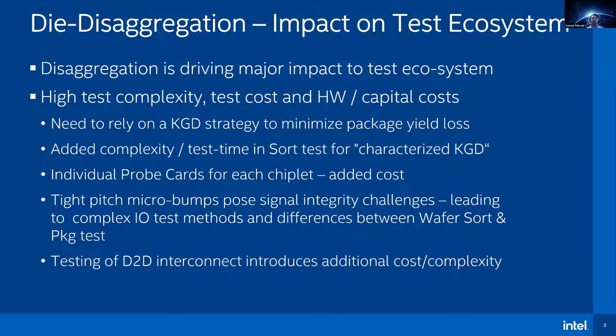How do you deal with interconnect? How do you test it? Do you test it? Do you have repair methods, repair technologies that are implemented? What impact does that have for test? What impact does it have on the die area, on the die design, DFT? So there's lots of considerations that have all of these vectors that impact our test ecosystem.